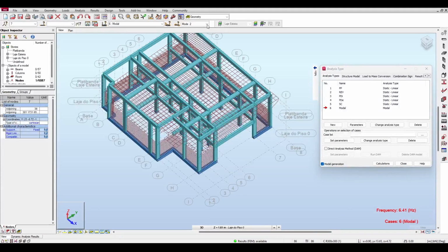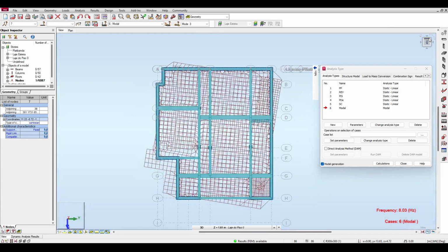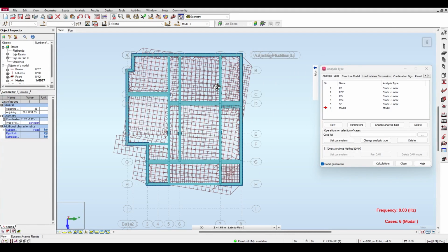Okay? Now, mode 3 is twisting because there was no movement. And you can see, yes, it is twisting. Now, I would think, wait a minute. I mean, obviously, masses are moving. Yes, but the center of gravity is not really moving. What I'm saying is, there are movements of masses to the right, and there are movements of masses to the left. They kind of cancel each other out in a twist.